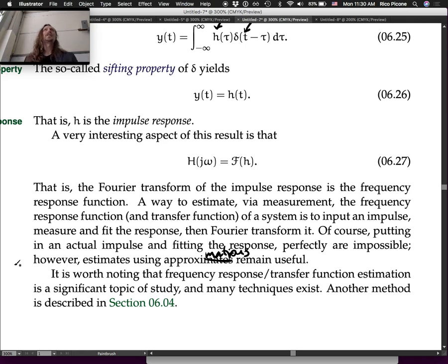It seems really theoretical. But when you have a system that's relatively complicated, and it's hard to break it down into its parts and analyze it, coming up with a nice theoretical transfer function to describe how it works, a lot of times you're stuck with just estimating its transfer function by measuring it.